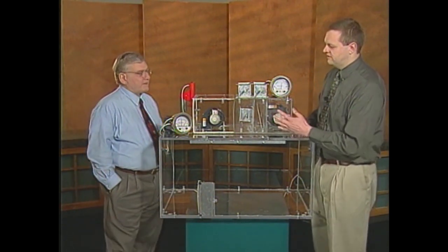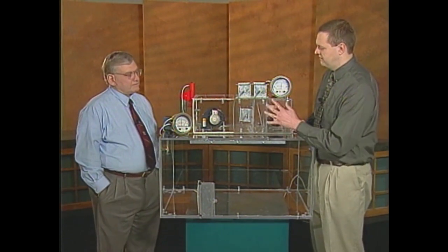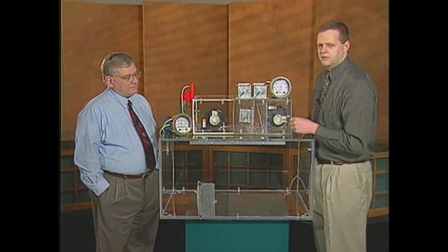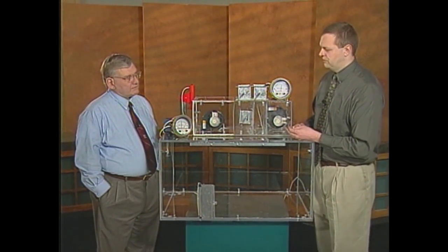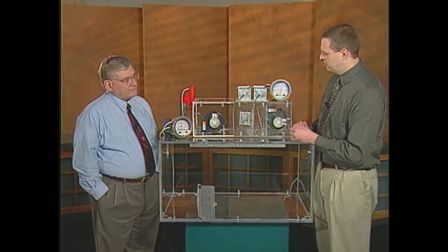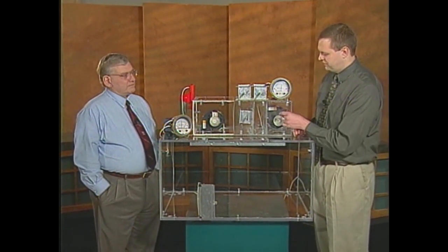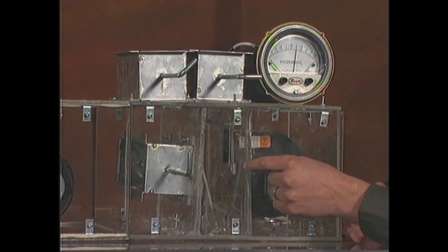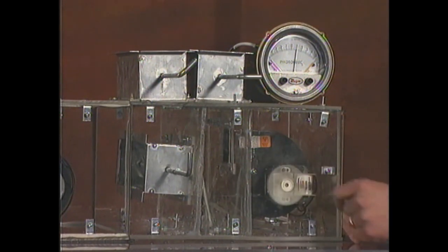Sure, Art. Just to know where we're starting from, at minimum outdoor air, we had the building pressure within our set point range that we want, between 0 and 0.1 inches. We're also controlling the return fan capacity to maintain about 1/10 of an inch in this return air plenum.